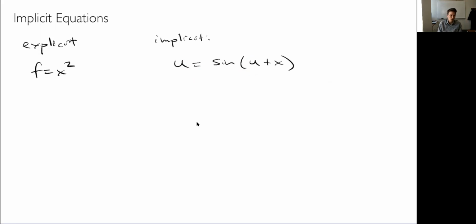You'll have seen this before in some different contexts, potentially. In the aircraft design class last semester, there was an example with a rocket, where the fuel weight the rocket required depends on how much structural weight there was. But the structural weight depends on how much fuel you need. So there's this iterative dependence. It's an implicit equation, so often we need to iterate to solve these.